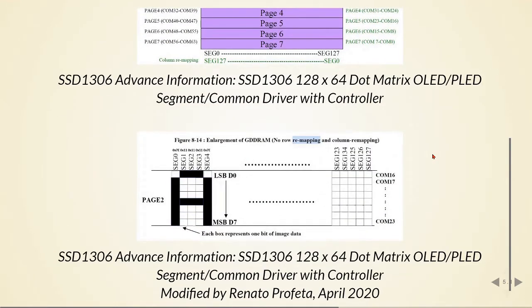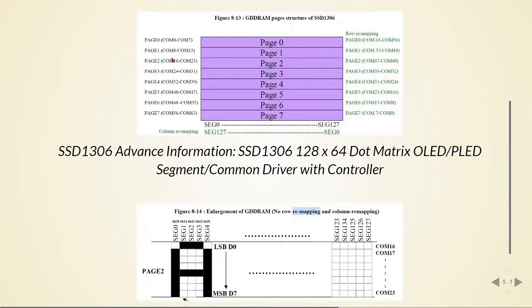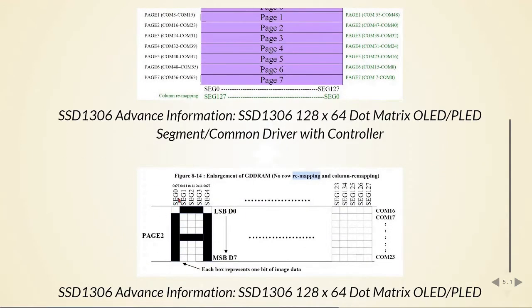We can demonstrate how to create a capital letter A. Imagine we are in some page, it can be any page. Then we have the segments, from 0 to 96 in our case, and then we have 8 bits, from bit 0 to 7. If we set some bits to 1 and some to 0, we can create different letters and different shapes.